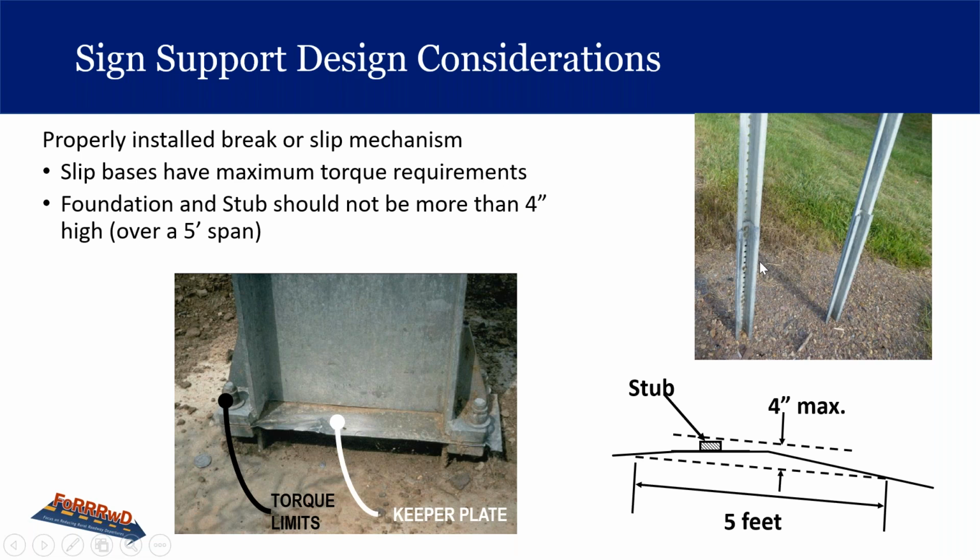And it even goes with trees. When you're removing trees alongside the road, you don't want to leave more than 4 inches of the trunk there because it could snag a vehicle, and it can cause an impact like a crash. So if you have it less than the 4 inches, then they can most likely clear it. But that's in the spec for this type of installation.